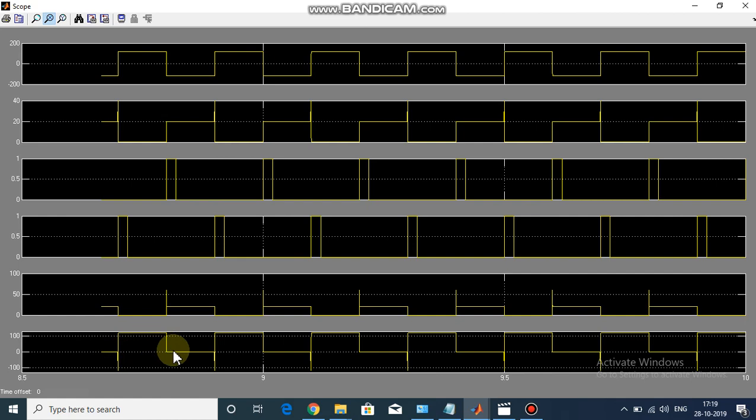So remember that the SCR voltage basically represents if the SCR is on or off. If the SCR is off, there will be full voltage appearing across the SCR. So don't be mistaken by the high peak. There is voltage across the SCR because it is off. So this is the off state of the SCR and this is the on state of the SCR.